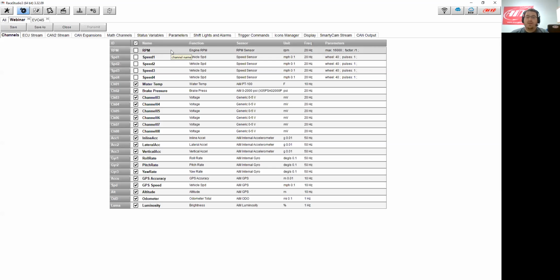That's going to include some open leads for power, ground, ECU, CAN high, CAN low, K line. Then you also have your secondary auxiliary harness. When you put these two together, it gives you a total of 8 channel functions. The primary harness will have 4 analog channels, well, analog digital, and we'll explain that. Your secondary harness gives you the other 4 channels, and there are ways to add more channels without the secondary harness, but all of the harness programming is found here.